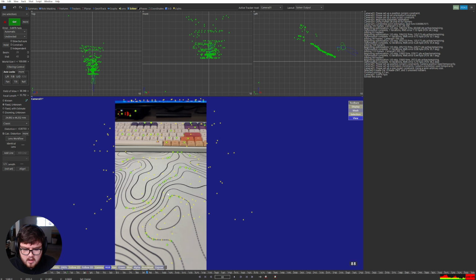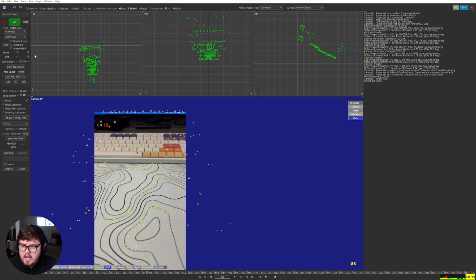And as you can see, it's gotten rid of some of the bad markers and also some of the bad frames. Some markers might be good for most of the frames, but then there's like 1 or 2 frames that go haywire. And so go ahead and delete that keyframe range. Shift G is to go ahead and solve that again. And there you go. We can see a big jump there, 1.9 solve error. I still want to get that down as low as possible.